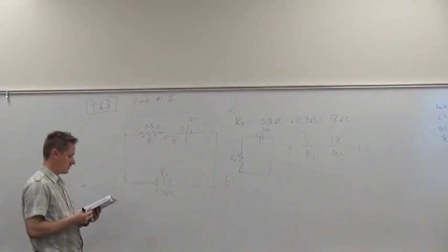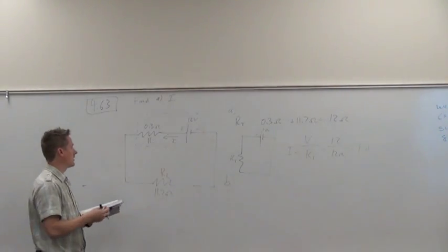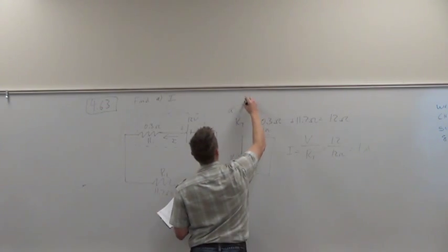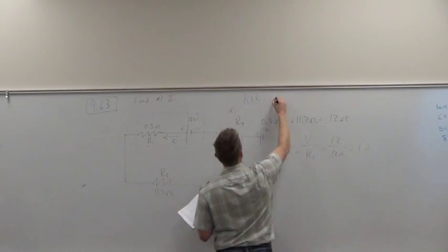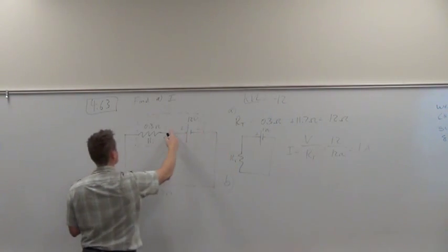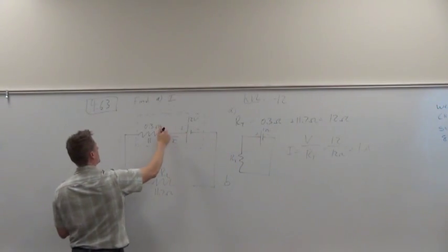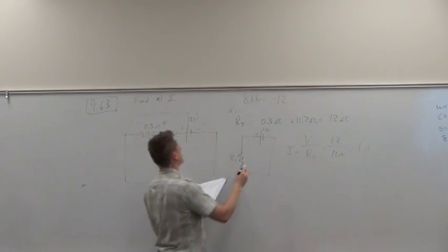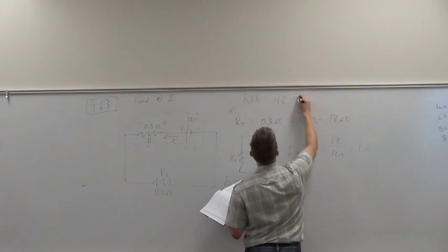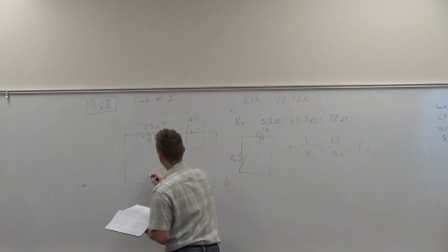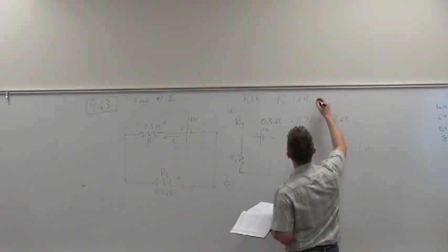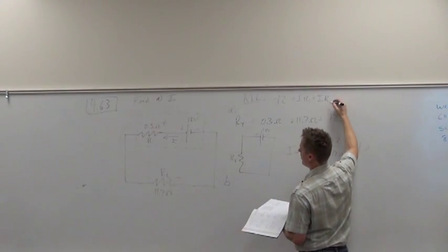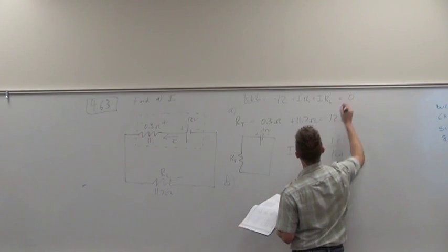Part B is, now another way, let me just show another way to do that problem, is just to use KVL. If you wanted to do KVL, you could say minus 12, going this way, what's the voltage drop there? It'd be I times R plus I times R, and then keep going around, just assign the correct polarities, plus I times R, where this is actually Ri, this is R, what, L. And then you can say equals 0.